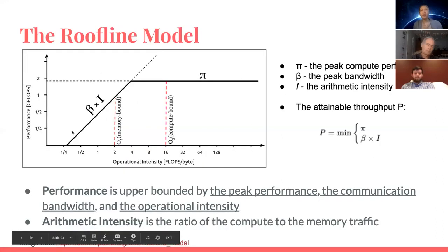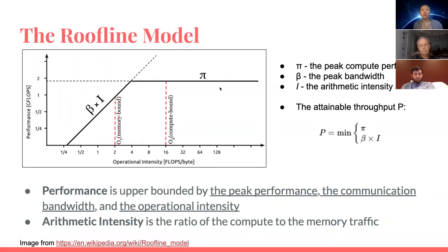In this case, the roofline describes what our hardware looks like, because when we design our hardware, we know how many PEs we'll have, which imposes how high the total flops will be. Flops means floating point operations per second. So how many PEs, compute units we have will determine this pi roofline here. And the bandwidth between these compute units and the DRAM will be determined by this tilted roofline. This slope will be the peak bandwidth of your memory to the PE.